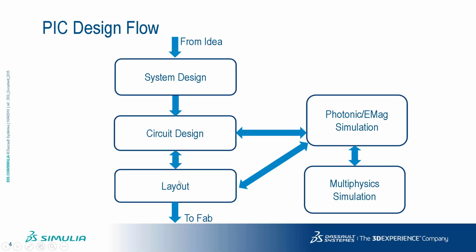But then there's also the layout phase. So after you've designed your circuit, you're going to lay it out, and this is where it becomes interesting for photonic circuits. For electronic circuits, you usually don't have to go back to the photonics or the electromagnetic simulation in the layout stage. But for photonics applications, actually connecting two components is a little bit more than just placing a copper wire between the two.